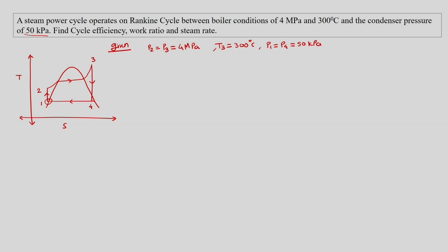So steam table, we had discussed that there would be different sections, and initially we would have a section where based upon the saturation temperature we can find out the enthalpy, entropy, internal energy, specific volume. In other section we had seen that we can find out the same parameters based on the saturation pressure. But after these two sections there will be superheated section where we would be given with saturation pressure and different superheat temperatures. For each case there will be same parameters as entropy, internal energy, specific volume would be mentioned.